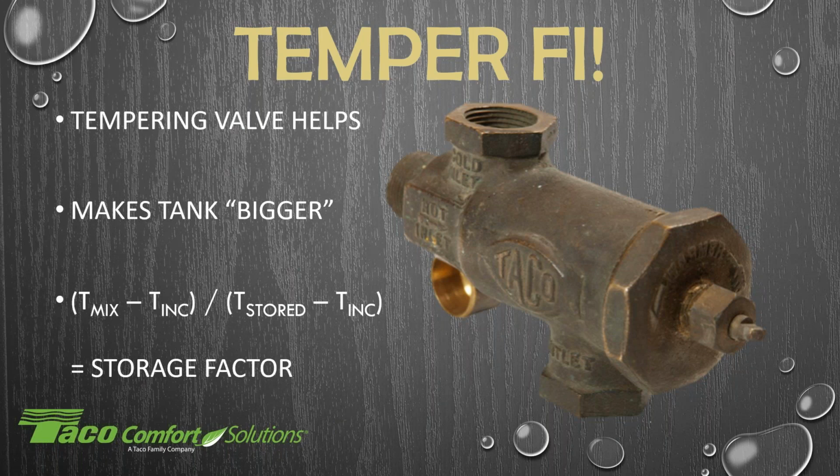We divide that by T stored, which is what we have in our tank itself, whether it's a water heater or an indirect tank, minus the incoming temperature from the street. That gets us our storage factor, which we will then apply to our usable capacity of the tank.